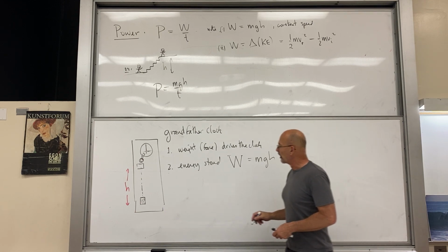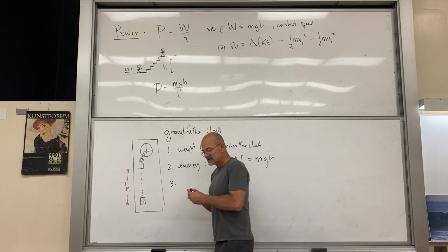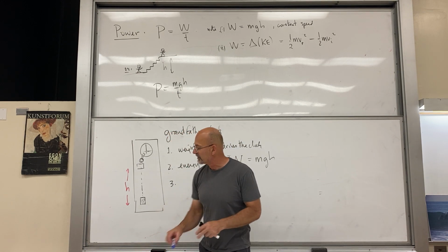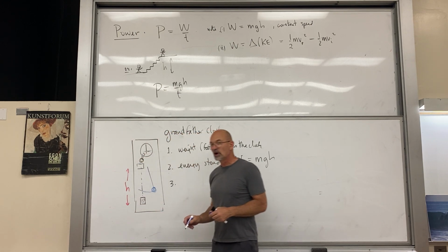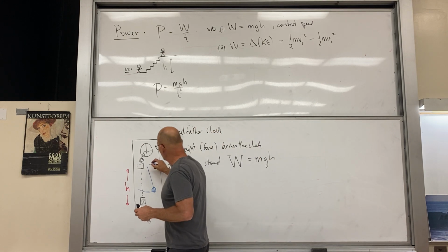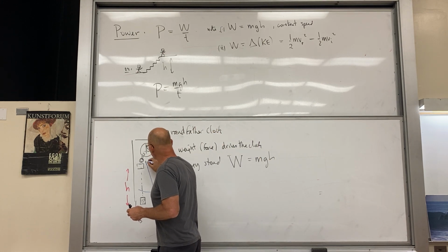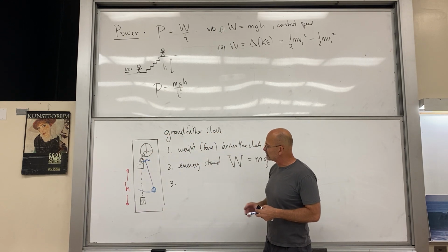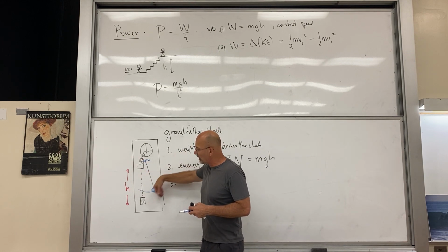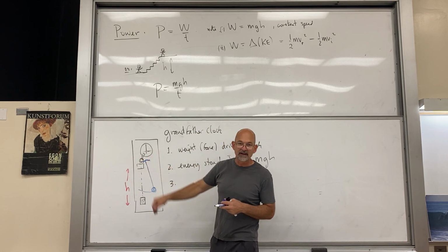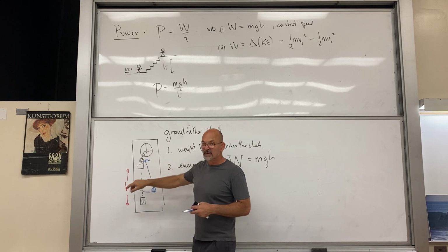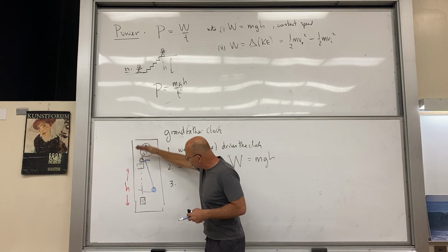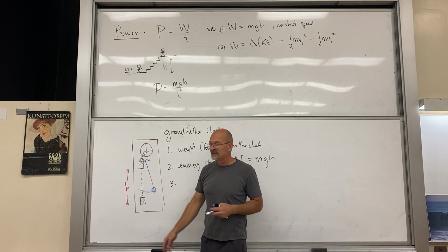Okay. What keeps time? Interestingly, what keeps time is a pendulum. So there's a pendulum inside the grandfather clock. It swings back and forth. You hear it go tick-tock. And this is also something you have to look up. The pendulum has a thing called an escapement attached to it. So as the pendulum swings back and forth, 1 second over to one side, 1 second back again, the gears are engaged and disengaged. So instead of this weight just going down and the thing spinning out in 5 minutes, it takes a whole week.